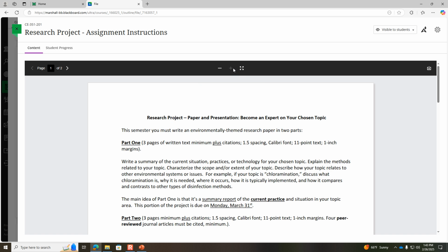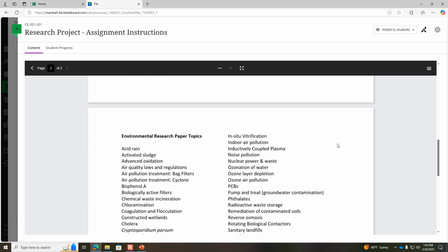What that is, if there's pollution, let's say somebody spilled dry cleaning fluid into soil. It's bad if that dry cleaning fluid gets down into the drinking water. And so if you have a pollutant, one of the ways to immobilize it is to take 2 electrical probes and send a huge charge and basically turn the soil into glass. So in situ vitrification is a way to try and trap a pollutant by turning the soil that it's in into a solid block of glass. So that's what in situ vitrification is.